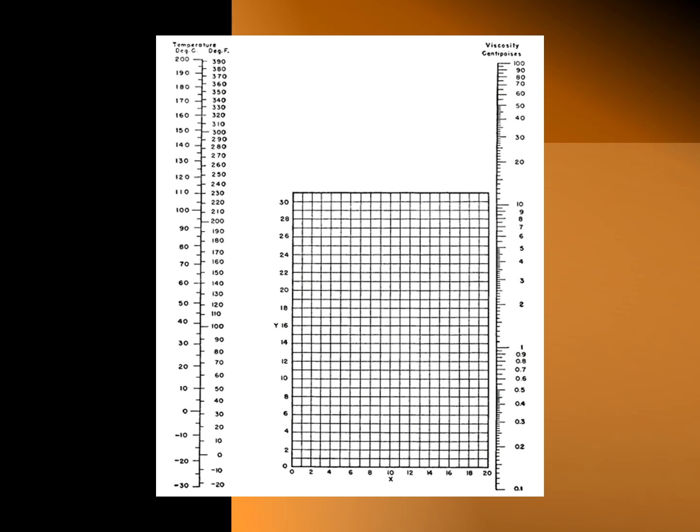This is the accompanying graph of the table just shown. We will use the coordinates we obtained from the table on the graph to determine the viscosity. On the intersection of x and y, connect it with the temperature and extend it to the viscosity line to read the value of the viscosity. I advise you to familiarize yourself with these tables and graphs found in the Chemical Engineer's Handbook.